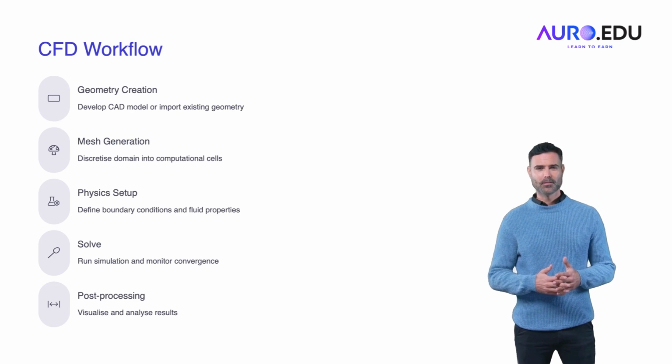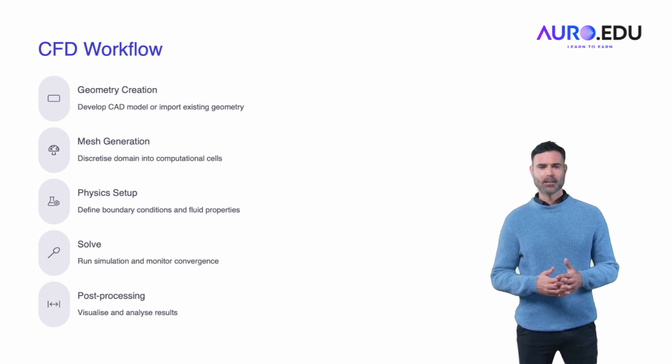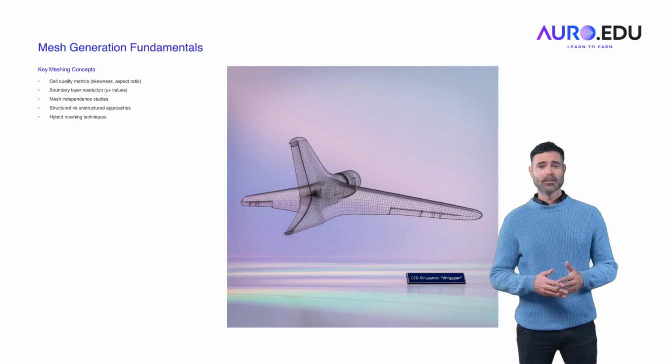Physics setup. Defining boundary conditions, e.g., inlet velocity, pressure, or temperature, and fluid properties, e.g., viscosity, density, and turbulence models, is essential for a successful simulation. Solving. The simulation is run using the selected solver, where iterations are performed until the solution converges to a stable state. Post-processing. The results are visualized, allowing engineers to analyze flow patterns, pressure distributions, and aerodynamic forces to make informed design decisions.